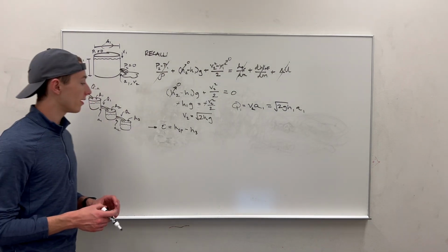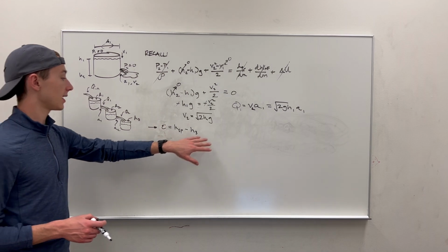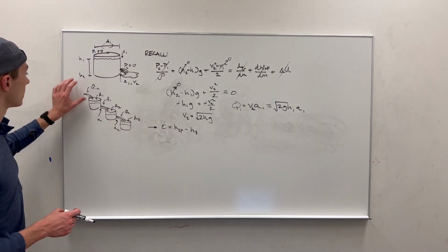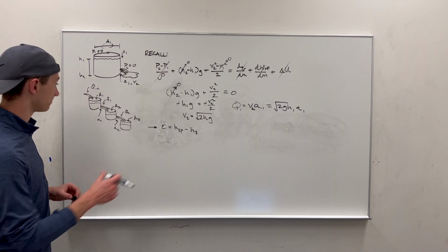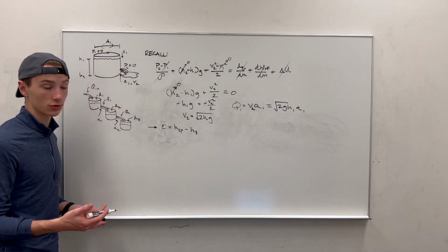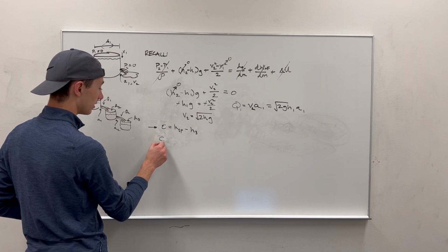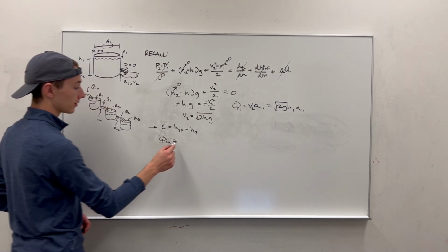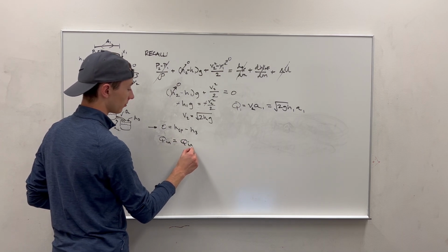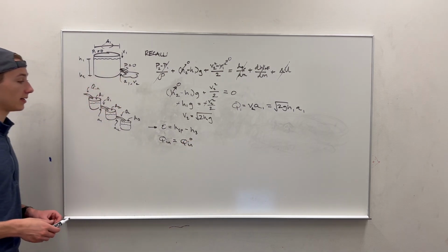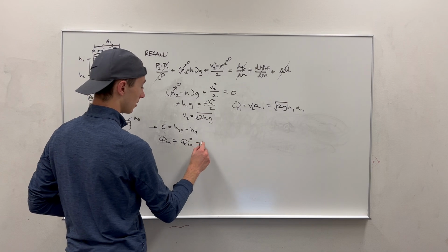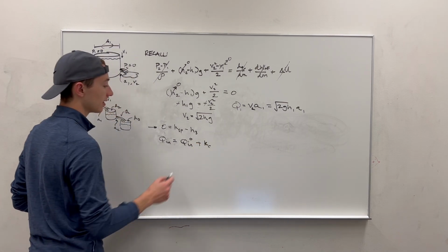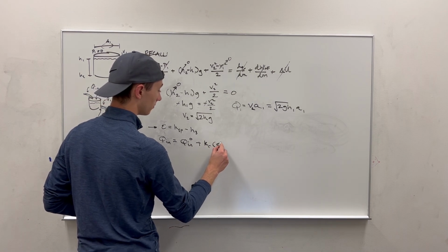So how do we go about minimizing this error between the set point and where the height of the water actually is based on the flow in the first tank? Well, you can say this is how a controller works, by the way. Q in is going to be equal to whatever you started with as the Q in, so we'll call it Q in naught, plus a constant which acts as a controller gain, we'll call it KC, times the error.